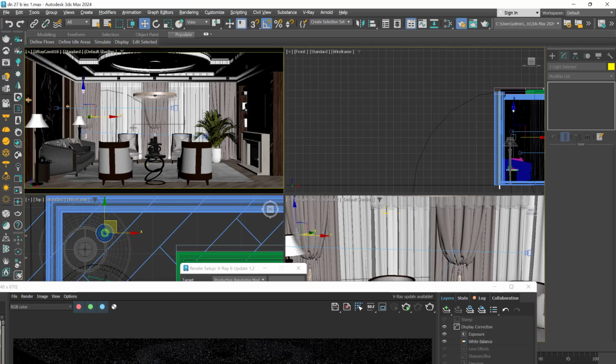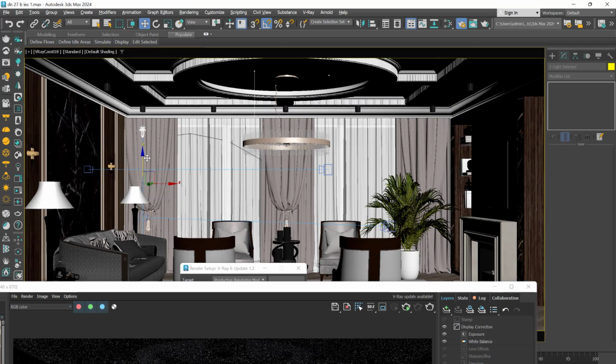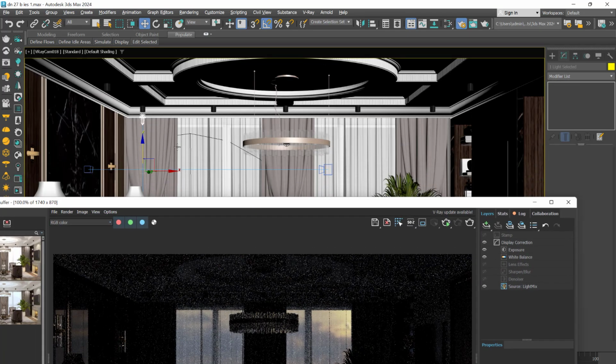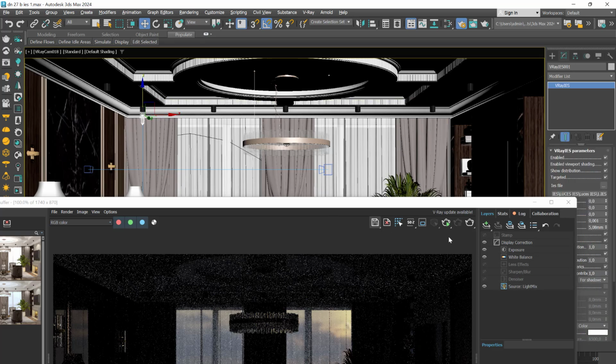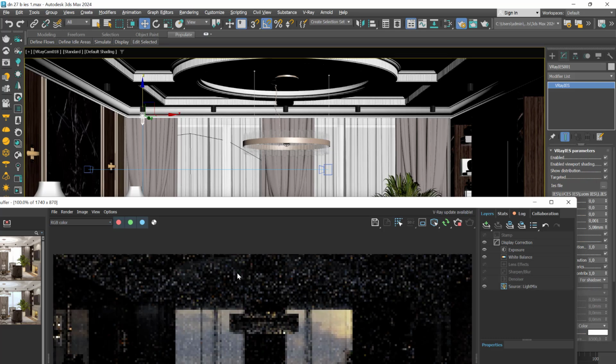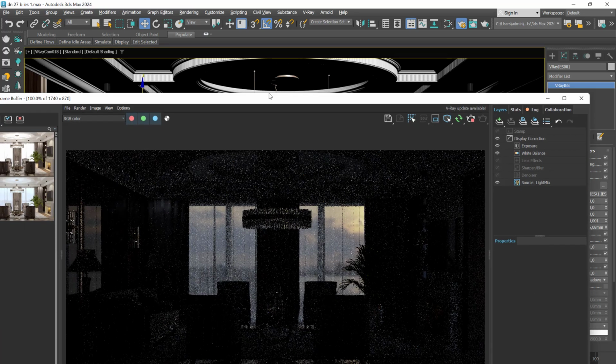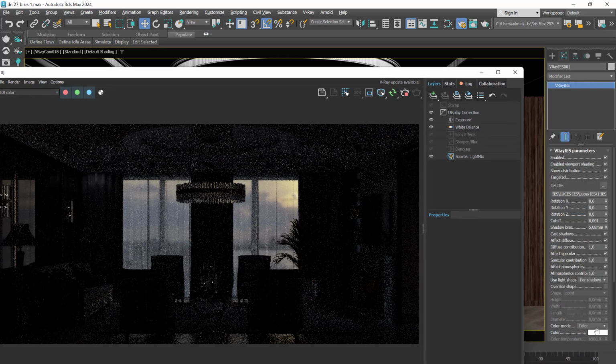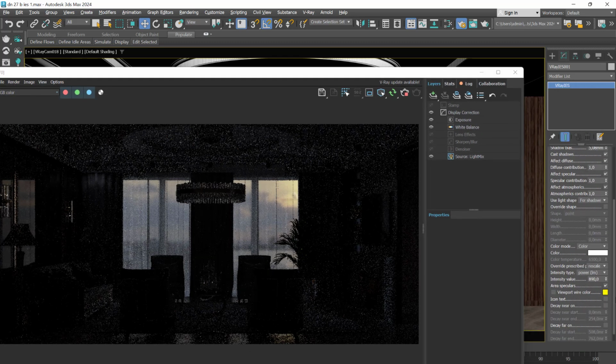As I said, I will install the Vray IES just right under our light bulb. And also we will have to raise this light source of this Vray IES close to our light bulb, so we can simulate that the light bulb is emitting this type of light or this decorative light. Getting rid of the distance between the light source, this Vray IES, and our light bulb avoids the problem of having an unrealistic effect when the light source is actually emitting light in the render a bit lower than its actual physical position. This is actually one of the reasons why I don't often use Vray IES.